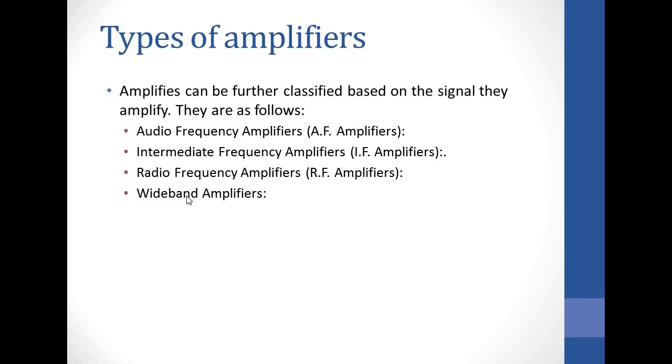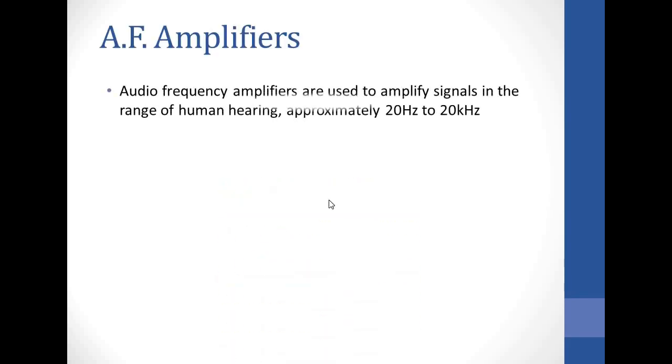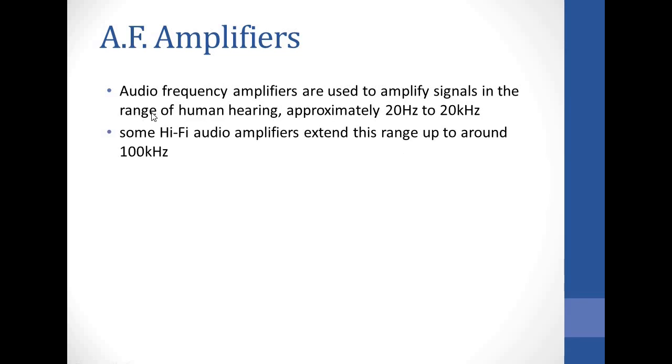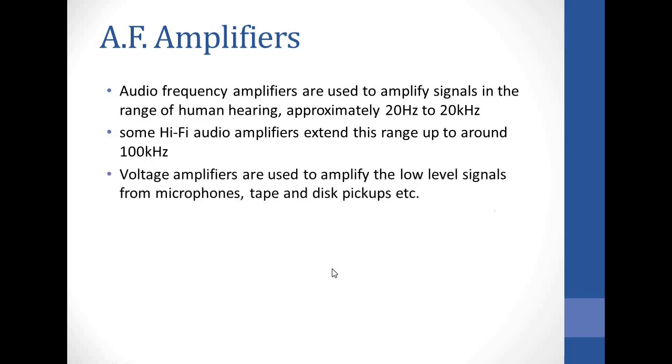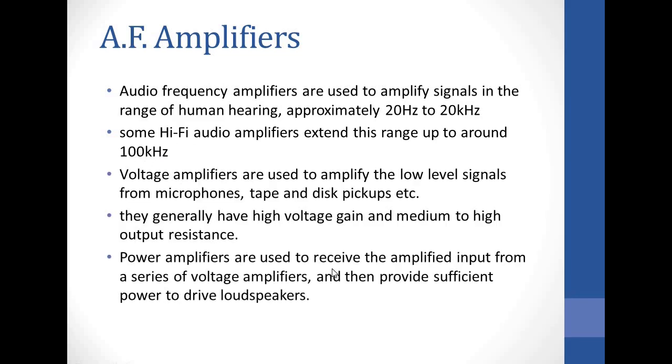The wideband amplifier is termed wideband amplifier because it can amplify a very wide bandwidth, a large number of frequencies. The bandwidth of a wideband amplifier is very large. So, in audio frequency amplifier, we said that it amplifies approximately 20 Hz to 20 kilohertz, and it is any signal within the human hearing frequencies. We also have a hi-fi audio frequency amplifier, which can amplify up to 100 kilohertz.